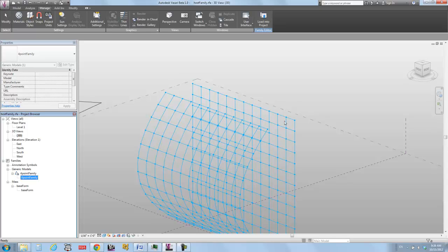Because we turned on our node points, and this is the thing, I'm sure that sometime this week somebody is going to say, all right, I made my component and I'm trying to put it on my divided surface and it won't stay put. And it's probably going to be because you forgot to turn on node visibility. It's just one of those gotchas that always gets people. So node visibility, you need that.